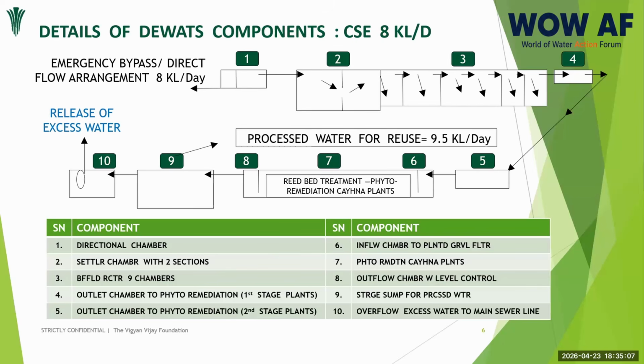As I mentioned to you, we'll have three levels of filtration. First, stones of around 4, 5, 6 inches, that is 100 to 150 millimeter size river stones, in the first phase.